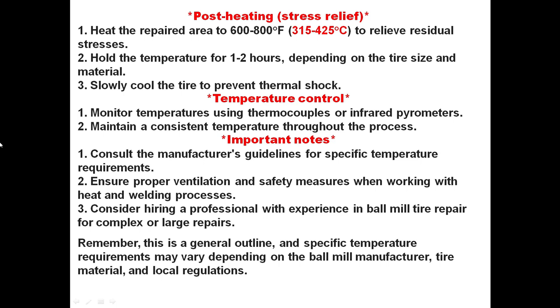And temperature control: monitor temperatures using thermocouples or infrared thermometers. Maintain a consistent temperature throughout the process. The important notes: consult the manufacturer's guidelines for specific temperature requirements. Ensure proper ventilation and safety measures when working with heat and welding processes. Consider hiring a professional with experience in ball mill tire repair for complex or large repairs.